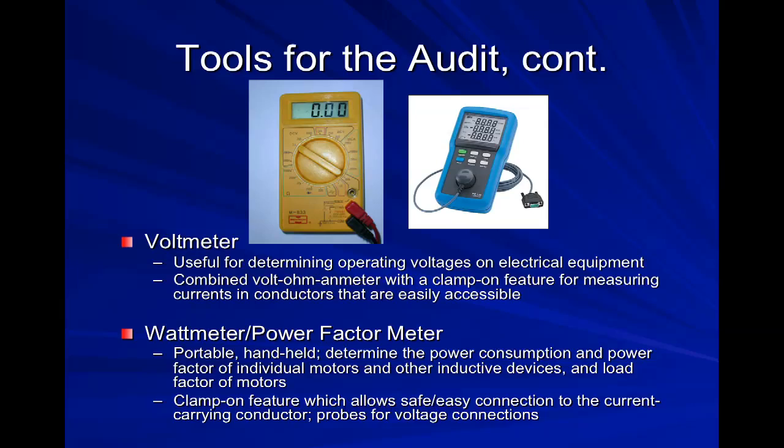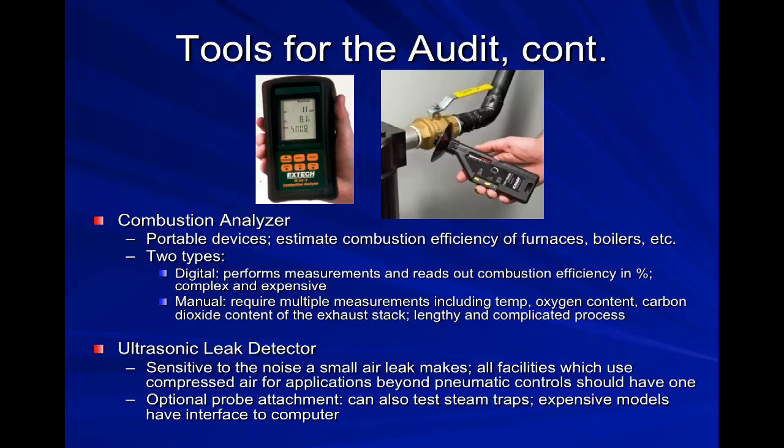We're going to have to measure voltage or power. It's really important to make sure that you are adequately trained on using this equipment for both safety and accuracy reasons. Other things, of course, maybe we're going to need to estimate the efficiency of boilers or air conditioners. Perhaps we want to measure if there are any leaks. We'll do this with an ultrasonic detector. There are other ways to do it, just simple soap bubbles or listening.